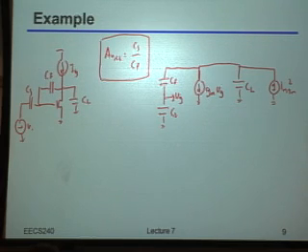So before I start doing KCL, KVL, things like that, I claim there's actually a very easy way to analyze this particular circuit. And to do that, I just want to ask you guys a fairly simple question. If I was to take a transistor and tie it into this diode configuration and look into the output resistance of that, what would it be? Yeah, it's 1 over GM, right?